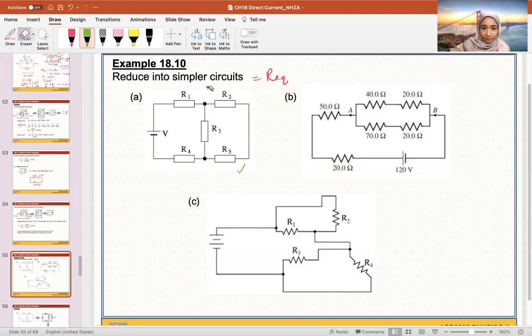That's all. Okay, don't use the hard way. It's already connected here. If I have I flowing, the same I will flow through R5. So we know it is in series. So R2 plus R5, you get R25. And then if I were to redraw this, this is R25.